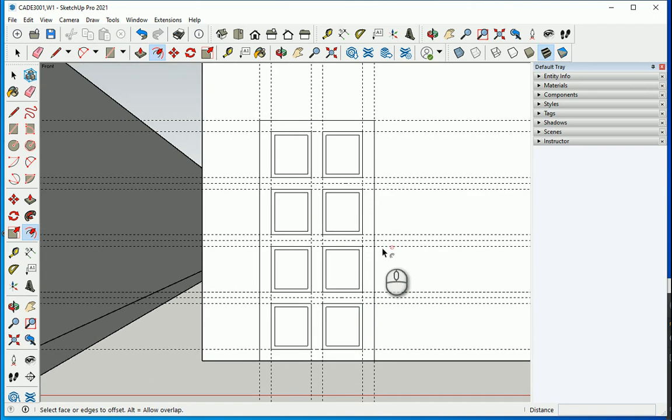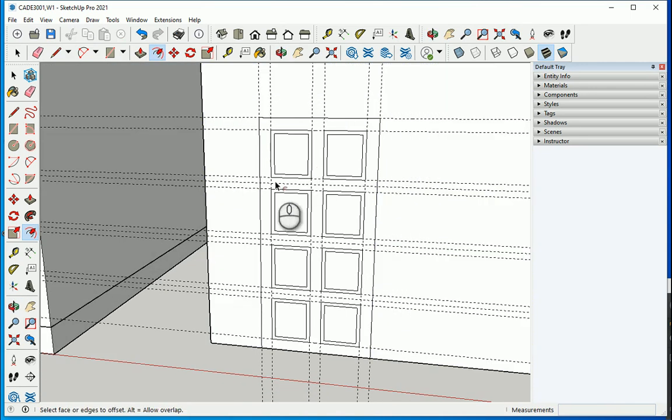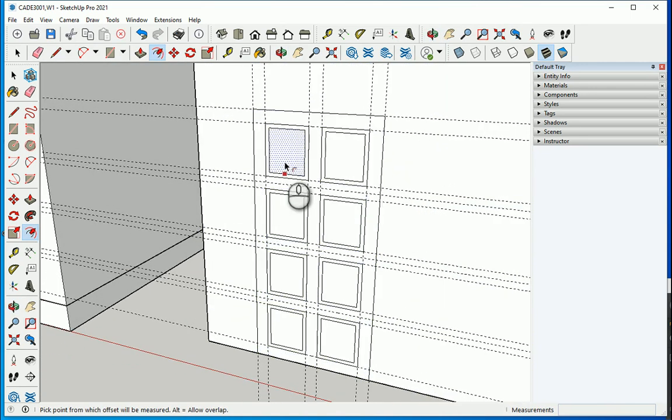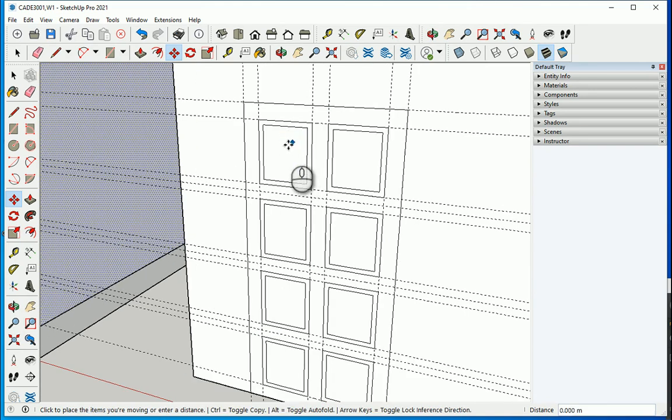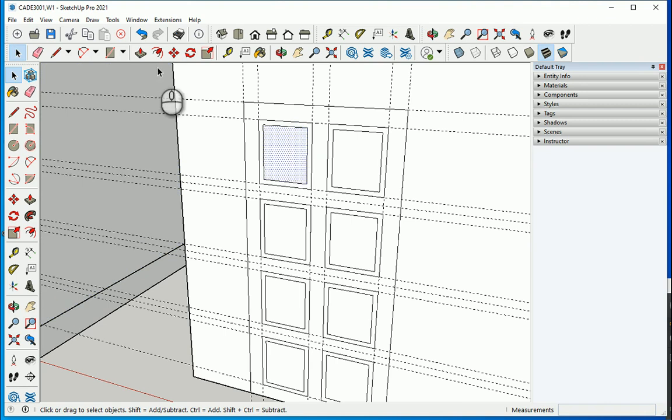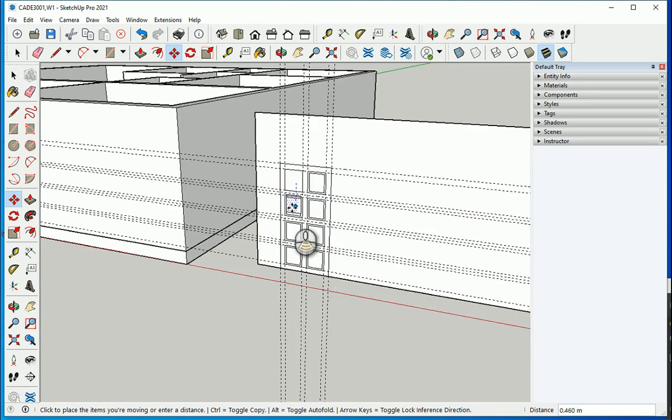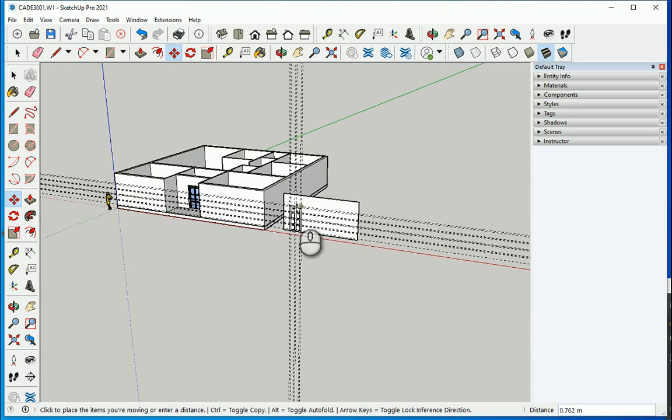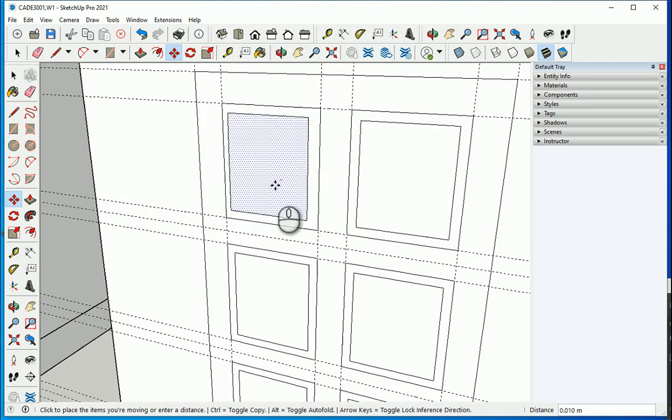Now, what's interesting here is the beveled part. I'm going to consider that these parts are kind of beveled, right? So I want to move them, using the move icon. When I select this surface to move, it's not going to move in the direction that I want, which is actually the green axis here, right? So how can you switch the axis? Just hit the left arrow key, and now you see that it's switching to moving in another axis,